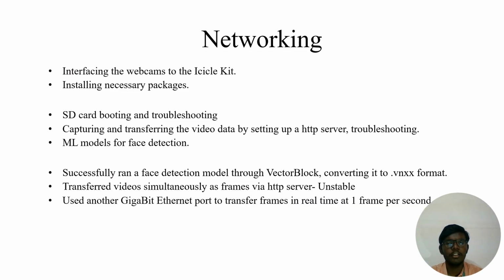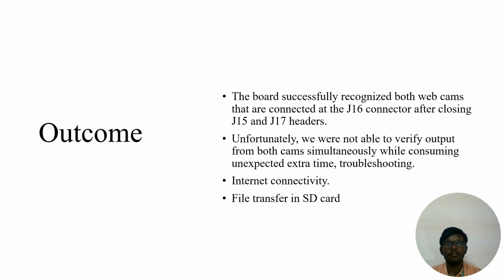So we went through another iteration of capturing the frames on a separate device and then transferring the frames to the board in real time over the network. This was a major part, where we interfaced two separate webcams to the Icicle kit and installed a few packages for file management in Linux systems. We tried SD card booting, capturing and transferring video data by setting up an HTTP server, running through troubleshooting, and then we went through ML models for face detection. And the outcomes.